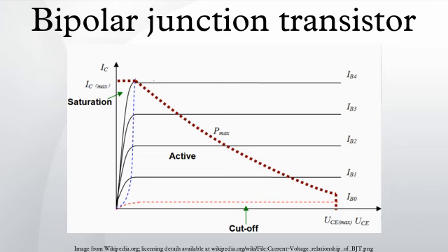In the NPN transistor in what is called active mode, the base-emitter voltage and collector-base voltage are positive, forward biasing the emitter-base junction and reverse biasing the collector-base junction. In the active mode of operation, electrons are injected from the forward-biased N-type emitter region into the P-type base, where they diffuse as minority carriers to the reverse-biased N-type collector and are swept away by the electric field in the reverse-biased collector-base junction.